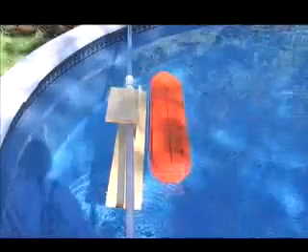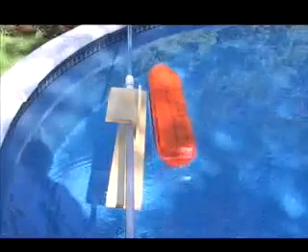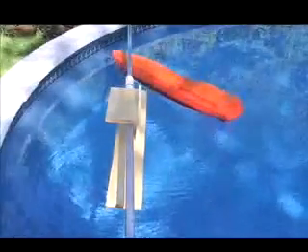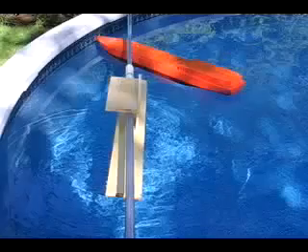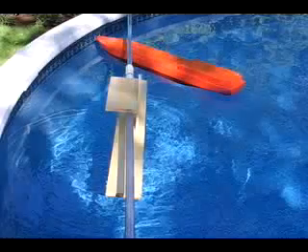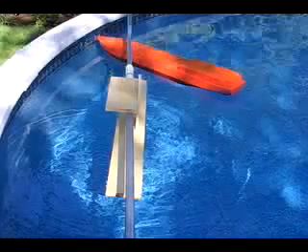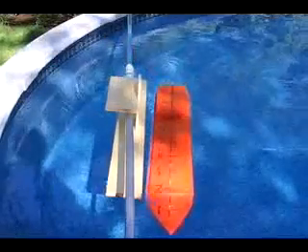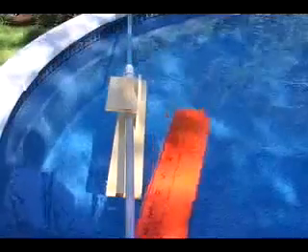Our small-scale model will turn around an open dock. When a third of the ship is clear of the corner, the ship will kick ahead on a hard-to-port wheel. As we have all learned, the ship clears the dock since the pivot point is about 1/3 from the bow when moving ahead. Here is another example.